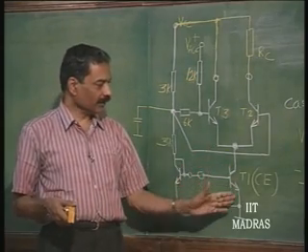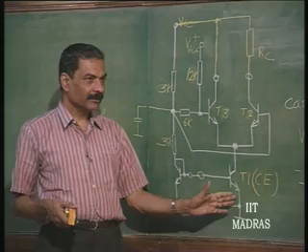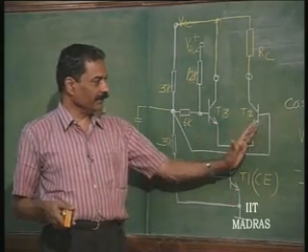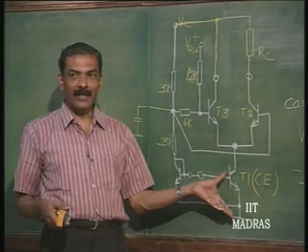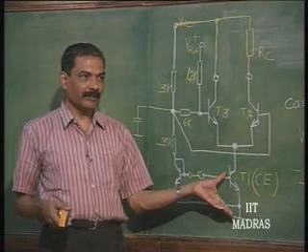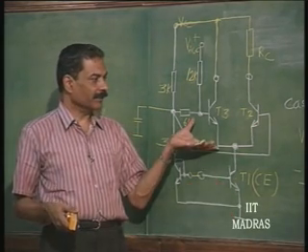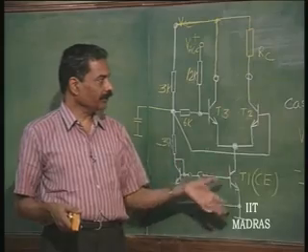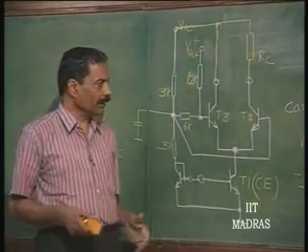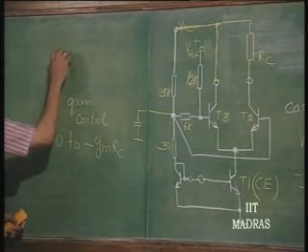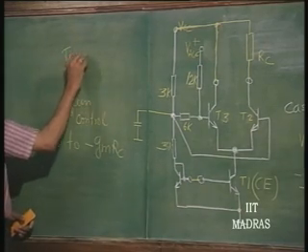Whereas here this current remains constant, and it is the division of currents that is changed, so that the parameters y11 and y21 remain the same when AGC takes place. That kind of advantage is offered only by this kind of structure. So, this is very popular in all tuned amplifiers.